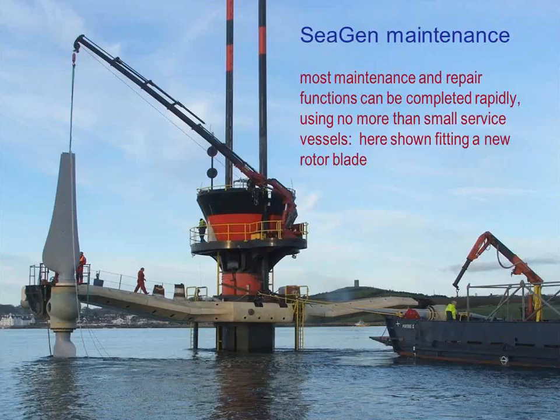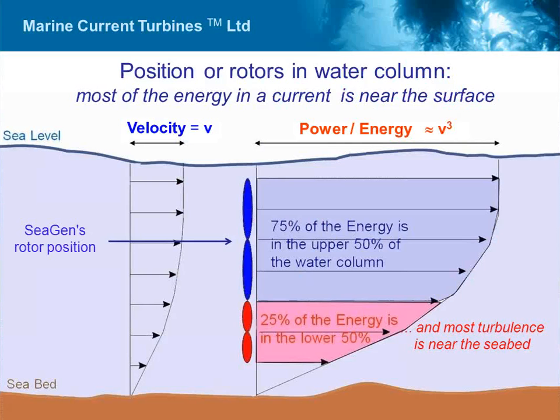As you can see, one of our benefits is that we can raise the whole of the operational components to the surface and maintain these using very low cost intervention boats. We don't have to drop any anchors on the seabed. We just tether the boat to the structure. We can use the onboard crane to remove blades. We've done drivetrain changes. We've done blade swap outs. And we can do all of the operation and maintenance very, very safely in this environment. So as an R&D site and an R&D facility, this is an excellent location.